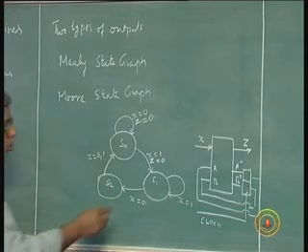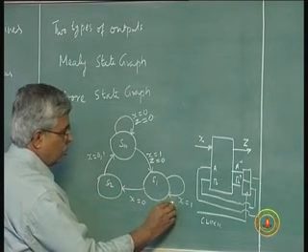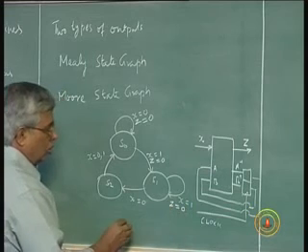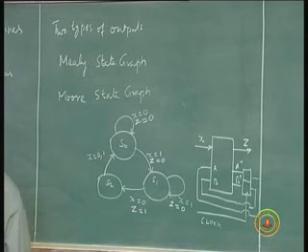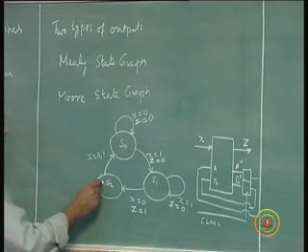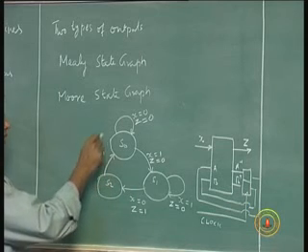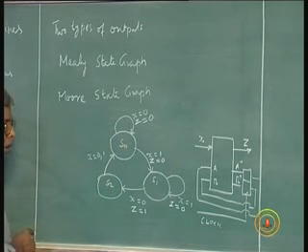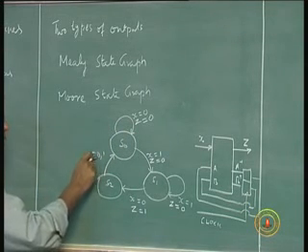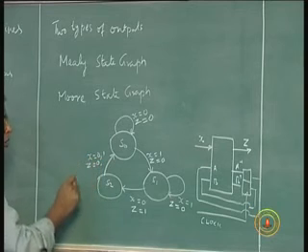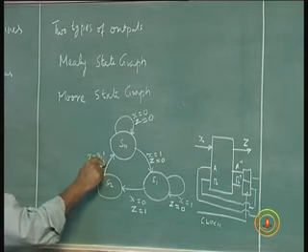On the other hand, for this one I may have Z equal to 0 and this I may have 1. Again, as an example, I have no circuit in mind. I don't know what it is going to lead to in terms of a realization. And when the circuit is in S2, whatever the value of X, it goes to S0. But I may say when X is 0, the output may be 0. When X is 1, the output may be 1.